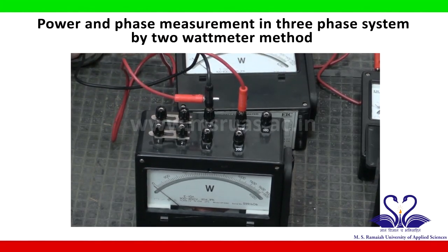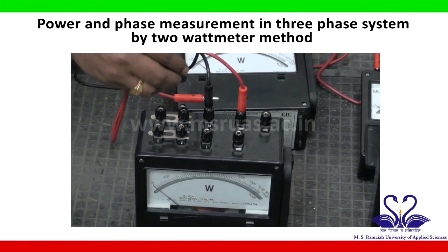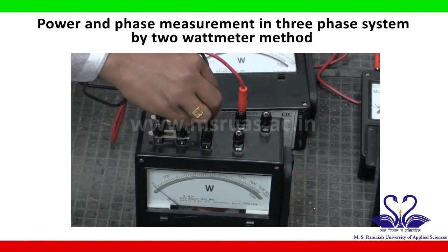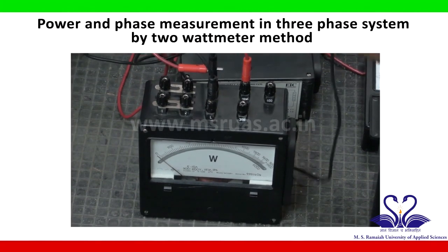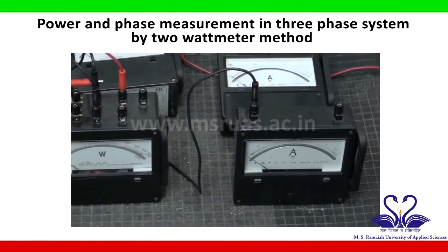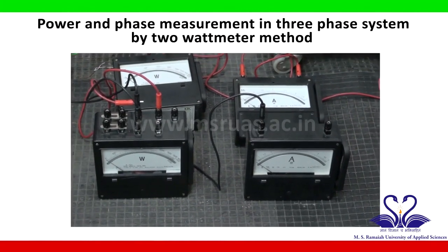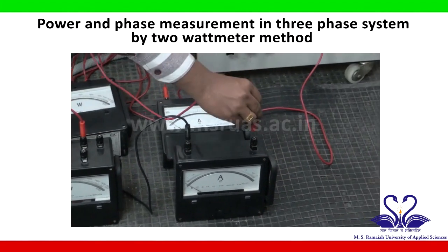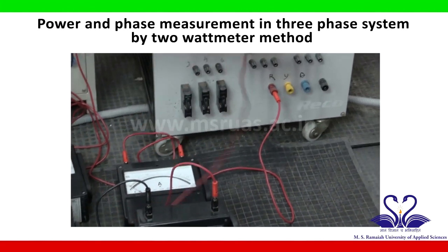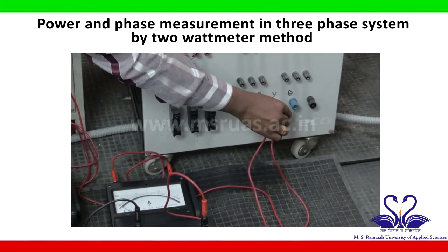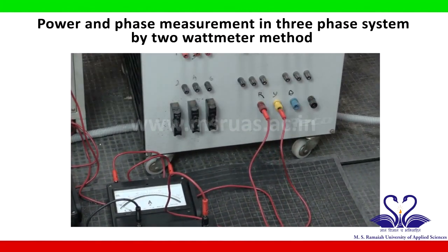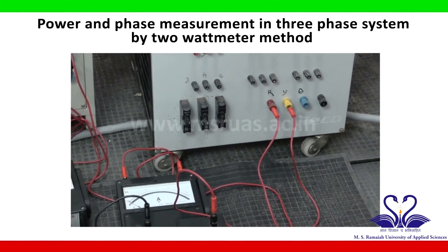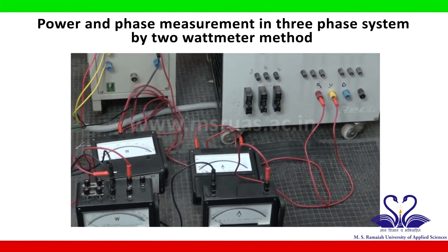Now the L terminal of the wattmeter to the ammeter, and the ammeter other terminal to the Y phase. These are the connections of the Y phase.